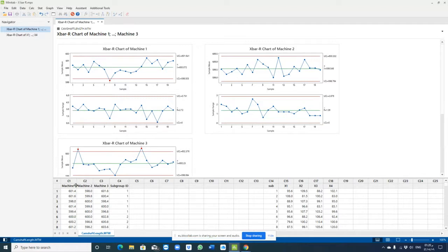Those are not samples, meaning that machine 1 has its own sample, machine 2 has its own sample, and machine 3 has its own. So we have 3 different control charts. So basically, you can delete those 2, and you can draw the control chart only for machine 1. This is one type of the data readings. You are collecting the readings from different machines or from different resources.